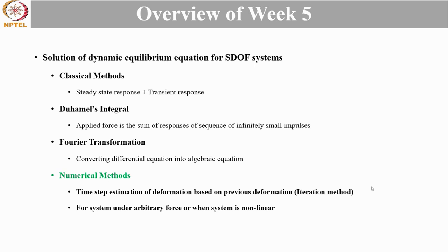The transient response is something which dies over time, and in the end only the steady state response prevails, that we saw in classical methods. Then there was Duhamel's integral, in which the applied force is distributed into small impulses, and the net response is the sum of responses due to these infinitely small impulses.